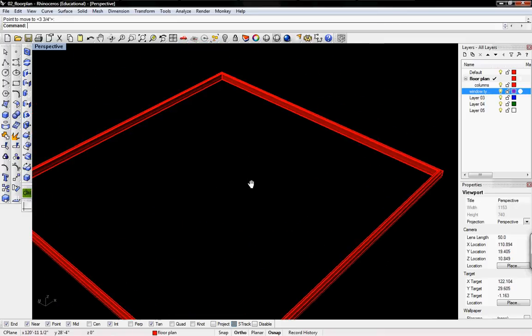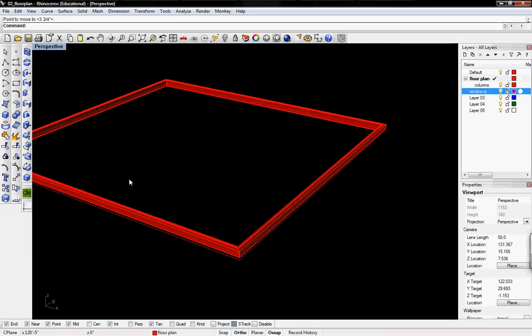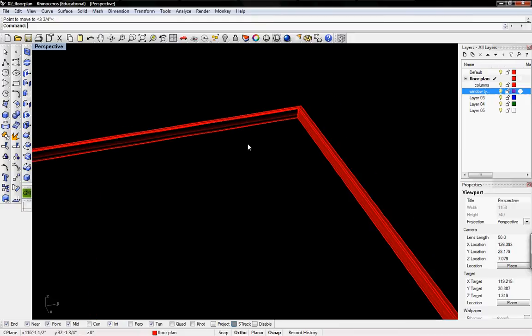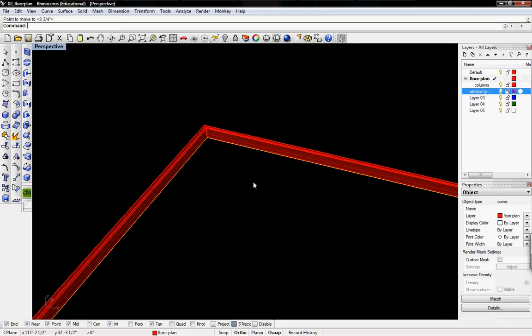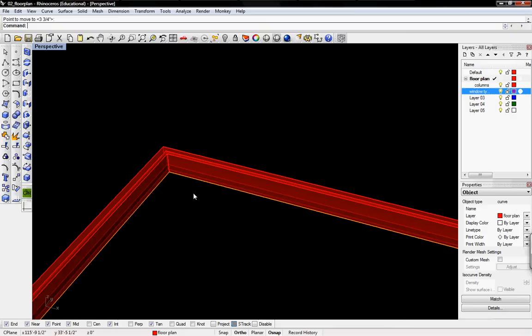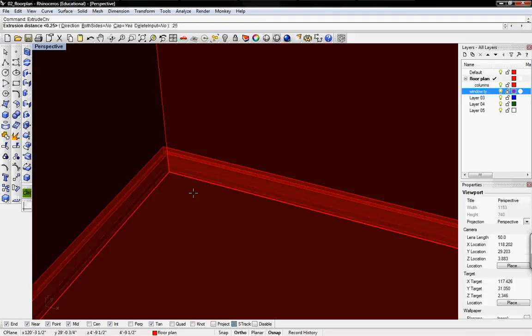And the next thing we need to do is create a window pane. There's one way you guys can get really detailed and create a quarter inch thick solid by using the innermost curve, or you guys can do just a 4-point surface and create the plane. I'm going to make a quarter inch thick glass pane, so I'm going to extrude the curve by 0.25 of an inch,